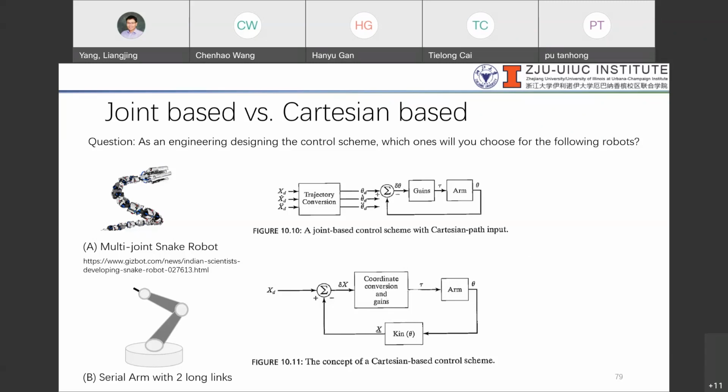So I guess a lot of you got this correct. Based on the polling, you don't want to solve for inverse kinematics when you have so many joints. Sometimes you need to consider redundancy, so the conversion is actually not very straightforward. And in the control loop, if you have to wait for it to finish in order to execute the next cycle, this is not going to be timely, so it will not work out that well.